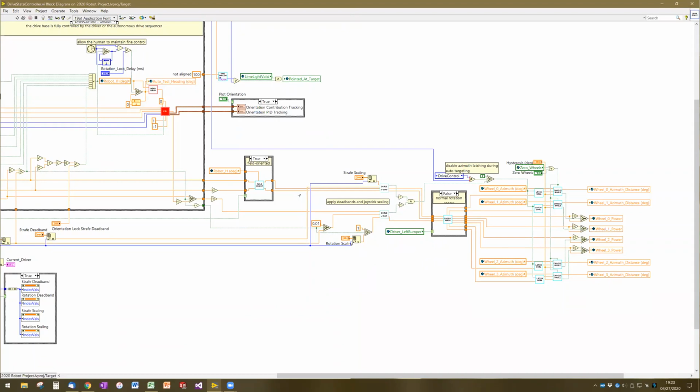So that's another reason to not drop the joysticks repeatedly. And we don't want the robot to move while we're doing that. And so we incorporate a deadband where if the joystick value is below a certain number, then we don't move at all.